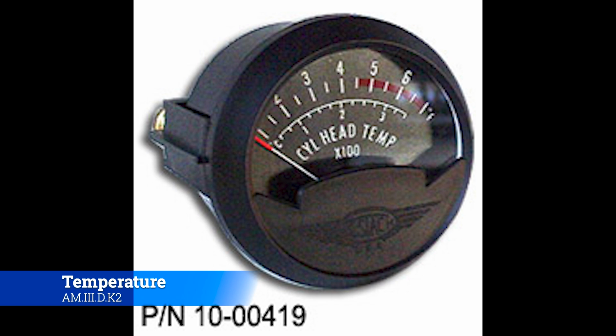Well, by itself, it can only really tell us something if it's really, really high or really, really low. But whenever you look at all the different cylinders, now you can start to see, hey, look, this cylinder is cool compared to this cylinder. Why? You start to try to figure out, is it missing every so many cycles? It's not firing correctly, so it's not generating as much heat. Are all the other cylinders just going bad, and this is the only good one, which is also a possibility. I'll give you a real life example of how CHT factored in.